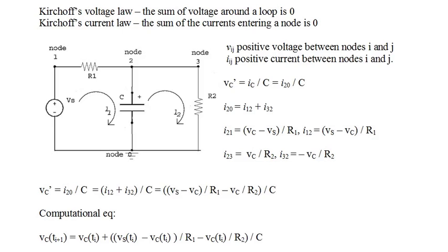The circuit shown is a low-pass filter. That is, when the input generated by the signal generator is a low-frequency sine wave, it appears at the circuit output, taken as the voltage at node 3, at close to full amplitude. When the signal is a high-frequency sine wave, its amplitude is attenuated.